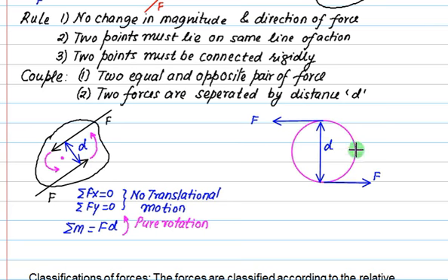We can introduce the pair of forces here also, one force like this, one force like this. You have to remove the initial pair, and now this pair will again rotate this object in an anti-clockwise direction. The meaning is that you can apply the pair of forces in any way you wish, but the distance has to be kept the same if the magnitude is the same. Otherwise, if you reduce the diameter, then what will happen to the force? This time the force F1 is greater than F.